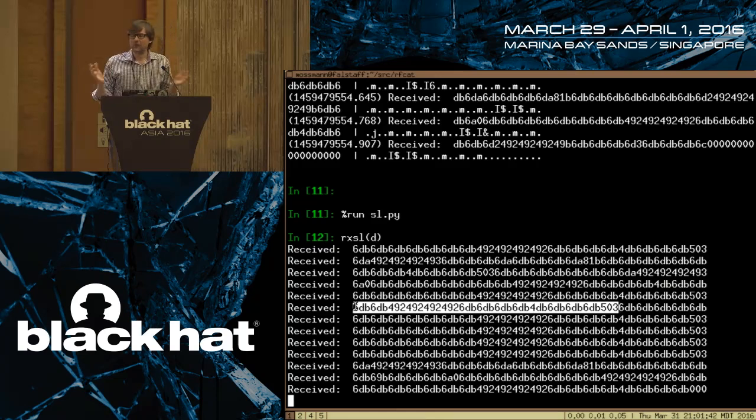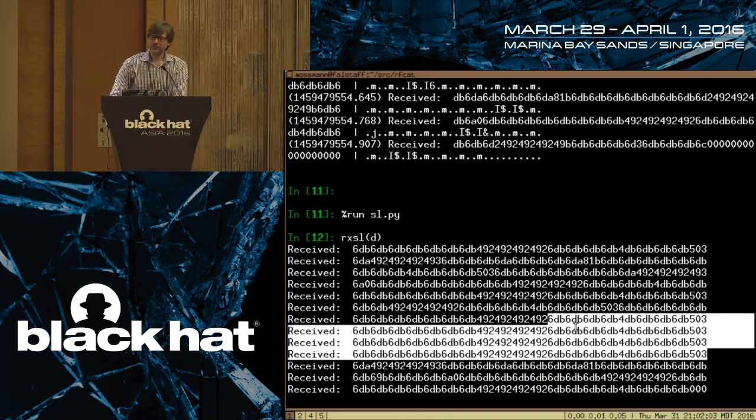Basically, I have a problem where that preamble matching, I'm configuring a sync word to be the beginning of the preamble, but it doesn't take very many bit errors to get a false positive match of that sync word. And since that preamble is so repetitive, sometimes I get a false positive match where I'm just out of synchronization. So most of these are good, like this block right here.